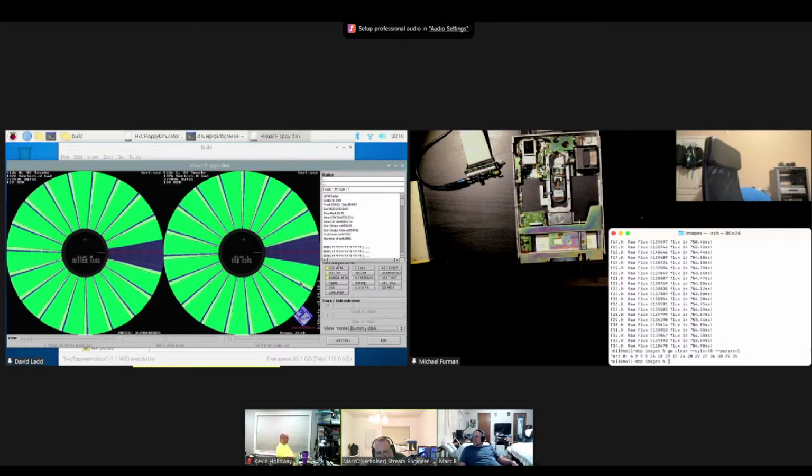I was gifted a North Star Horizon system with 2 SA 400 drives in it. Do they have 2 index holes or just one? It only has 1 index hole, but it definitely has hard sectored marks on all the floppies. So it has the start index hole, and then one every sector.